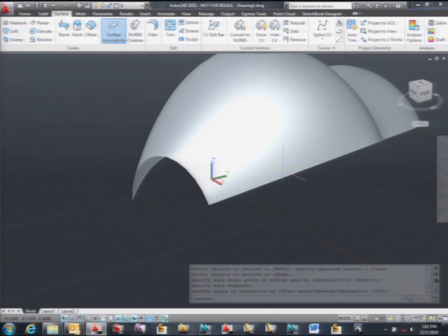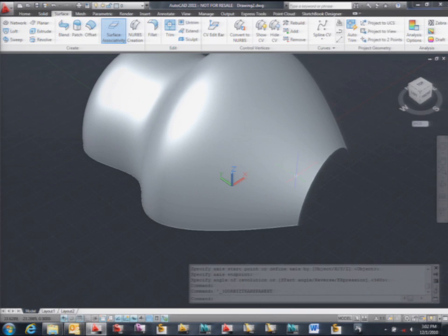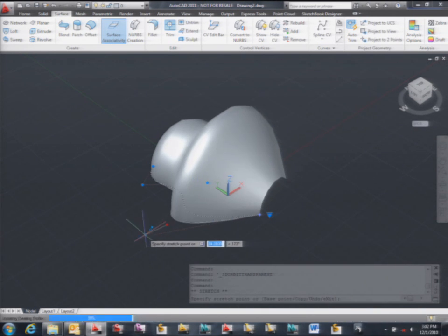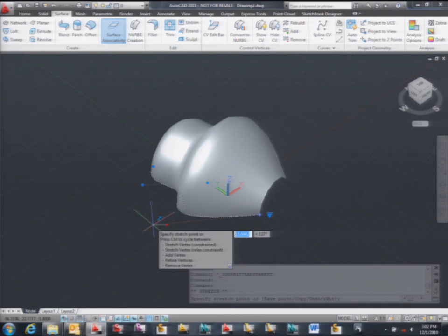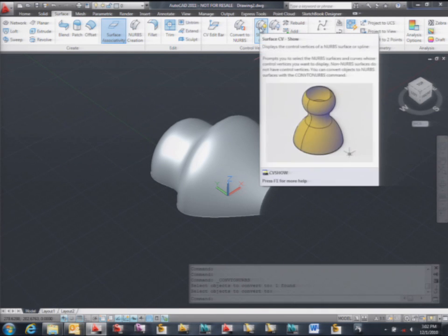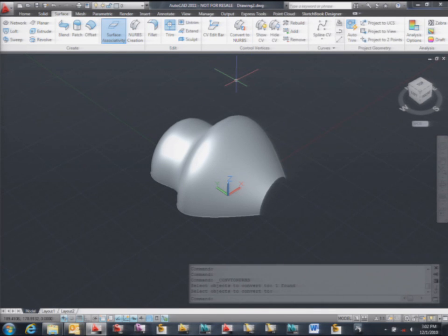Okay, and this is what I have, right? As I told you, if the change that you need to make can be described by the surface, the revolution like this is the best method you will ever get to make that change. That said, if what you want is, for example, something here, and not here and here, which is what revolution would do, then you will convert to a NURBS surface. When you convert to a NURBS surface, it looks like nothing happens, because again, as I told you, the explicit surface is a NURBS surface with a wrapper on top of it that says, okay, you are a revolution, right?